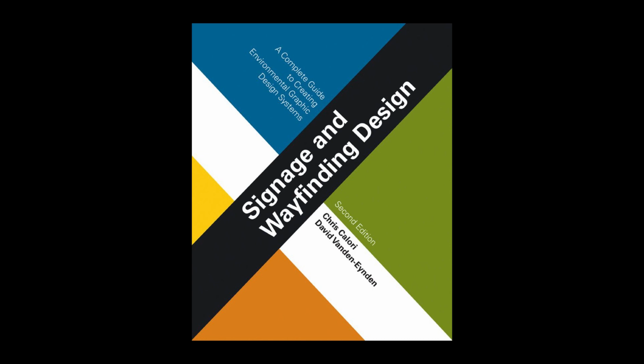Required submittals indicate which drawings, samples, and other items fabricators are to submit for design review as they produce the project. Submittals required for signage typically include shop drawings, artwork for all sign graphics, material, color, and finish samples, product literature, and production prototypes. Quality/workmanship standards describe general standards for the quality of work to be performed by the fabricator, such as tolerances, accurate fitting of parts, use of non-defective materials and components, production and finish standards, and more.